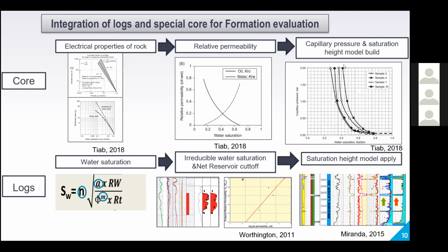Moving next to the capillary pressure data. The capillary pressure is based on injecting the sample. The samples are saturated with water. In the porous plate method, I saturate the sample with 100% water and start to inject gas. The injection of gas starts to displace the water.